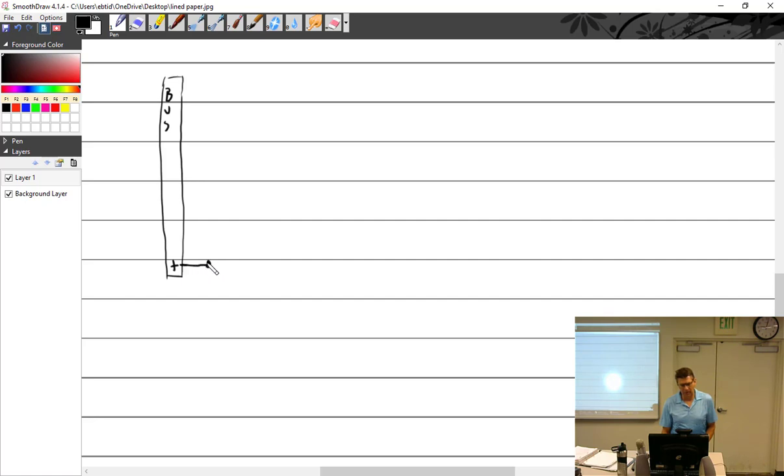So I would have a master switch. No, I gotta do this right. Let me think about it, because I wasn't planning on doing this. I have a master switch. We'll put it right here, master switch. So when I turn off the master switch, the airplane dies. There's no electrical to anything except the clock. And the clock comes right off the battery. And so I got my battery, speaking of my battery.